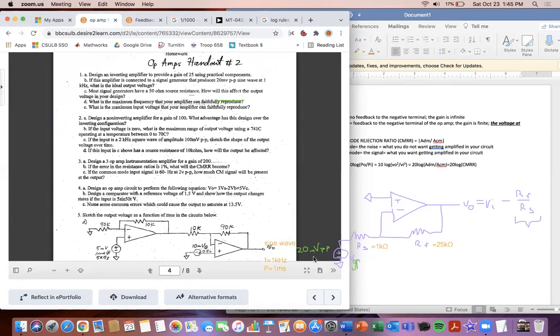And now that I know that, I can draw sort of what this voltage generated looks like. Okay, so let me get both of my graphs here. Let me do the voltage on this one and the time on here. I'm going to do my time in milliseconds for you guys. And we know the period is 1, so I'm just going to do it right here, 1, and then I'll have 2 here. And we have 20 millivolts peak to peak. So that means 10 millivolts up, 10 millivolts down. Oh, sorry, that's one. So 10 millivolts up, 10 millivolts down, 10 millivolts up, 10 millivolts down. Now that we know we have 10 millivolts here, and we have negative 10 millivolts here, because this is our voltage in millivolts. And we know this is the V generated graph.